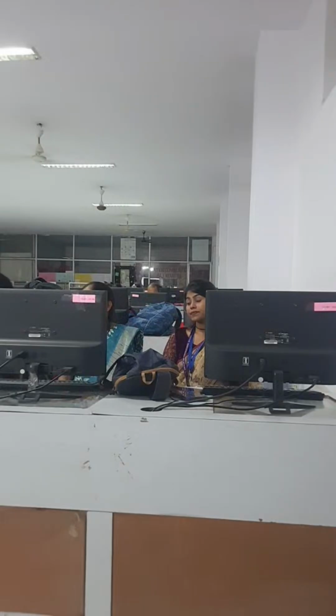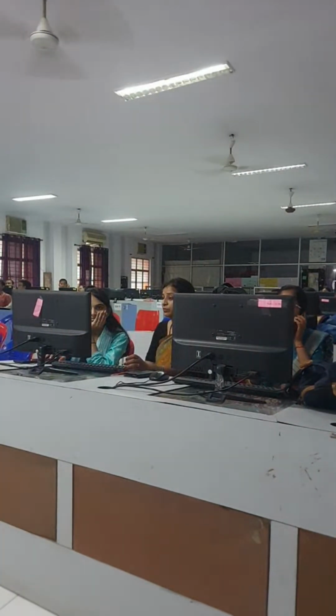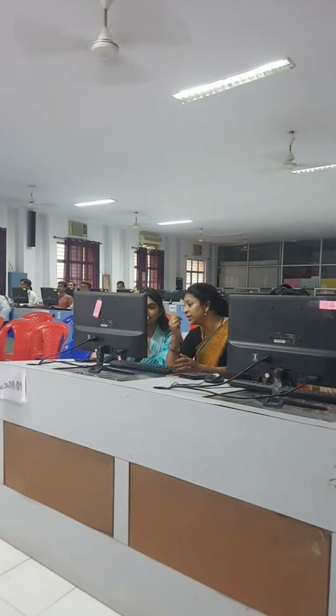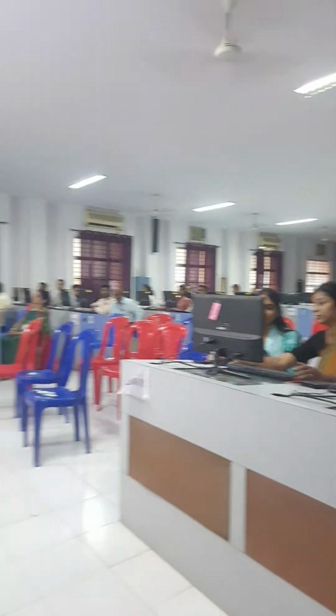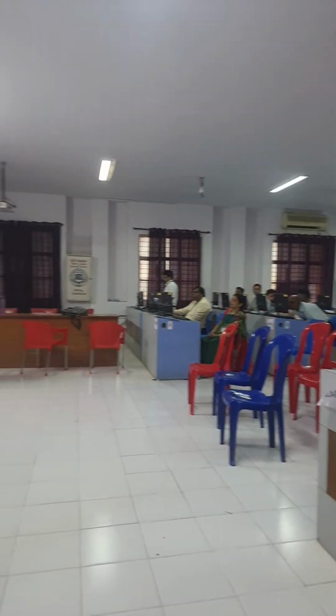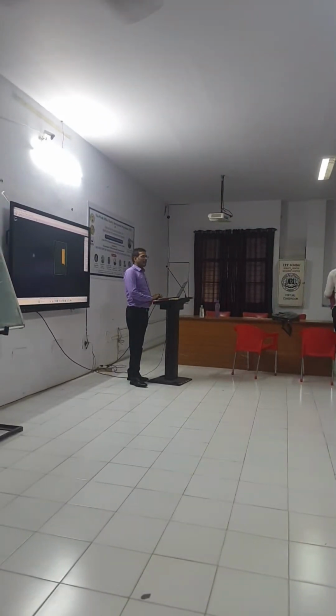Okay. So see, on the right side the N-well is given. So first you can draw this N-well, because PMOS can only be designed inside the N-well. Getting my point? So in that N-well, how can you design a PMOS? Put a P diffusion here, like this. This is the P diffusion.